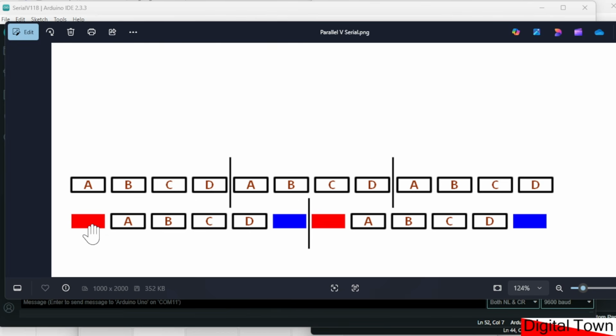Now I've given the packet start a value of 255, but especially part D, if we're just doing a counter, part D is regularly going to get to a value of 255. So it would be quite easy to fool the system, and it would think that if it picks up byte D, right, I've got the start of the packet, and it then starts working its way through.